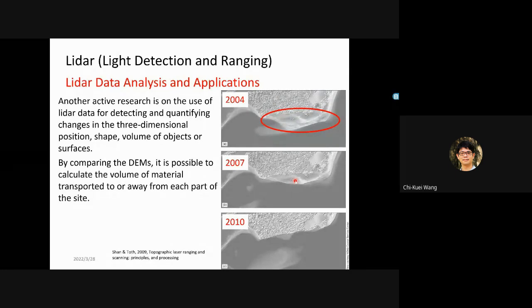I know in previous weeks you had photogrammetry. Sandy beach is actually quite challenging for photogrammetry to make a 3D model. But for LiDAR, as long as the surface reflects, the 3D model is there. So this is where the LiDAR data would be useful.